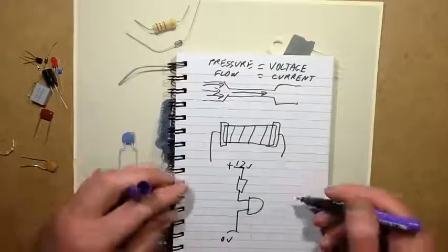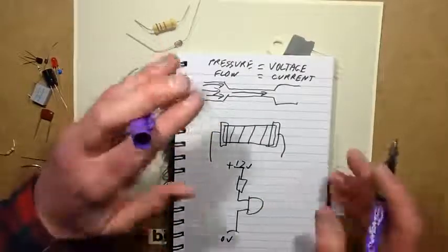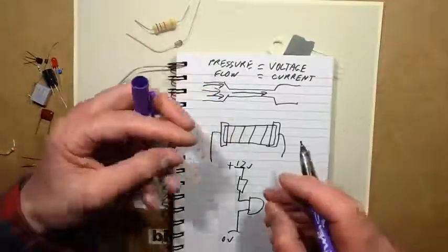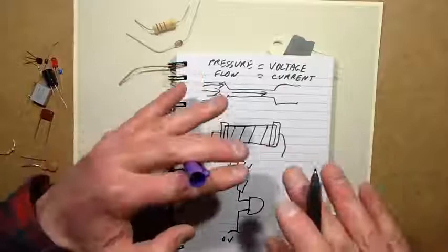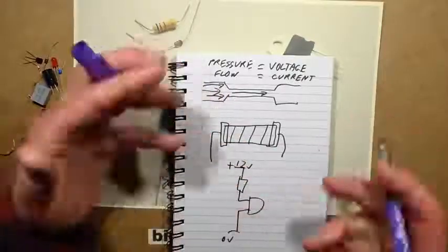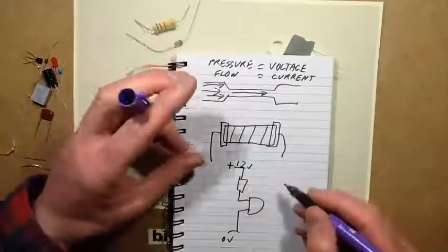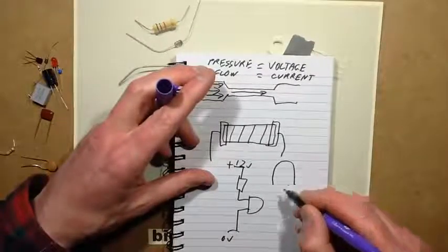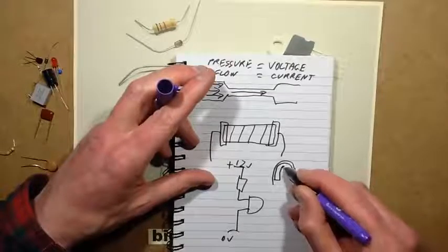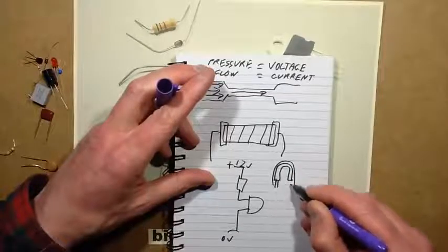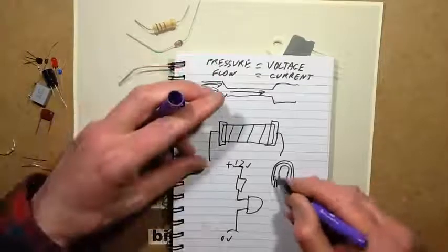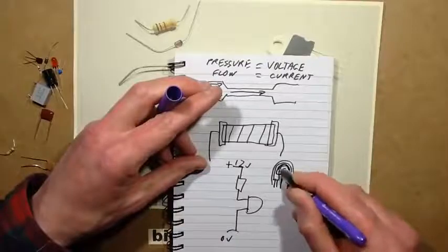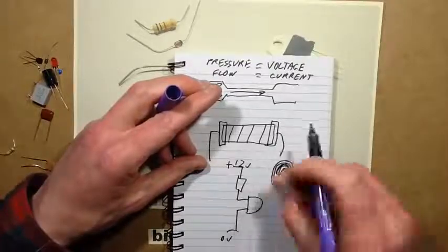They're also used for things like time delays. You might have a resistor charging up a capacitor, you know, it trickles the current into it until the voltage reaches a certain level, and then that could be used as a timing function. And you also get variable resistors where effectively it's a carbon track connected at both ends. You only really need to connect at one end, and with a wiper that wipes round that track, depending on its position, that will vary the resistance.